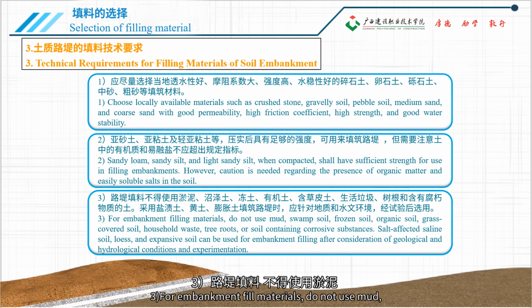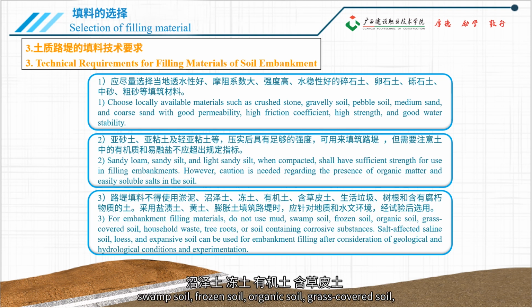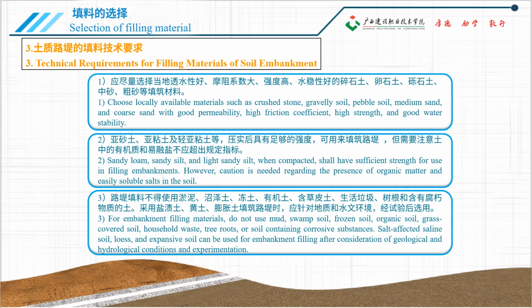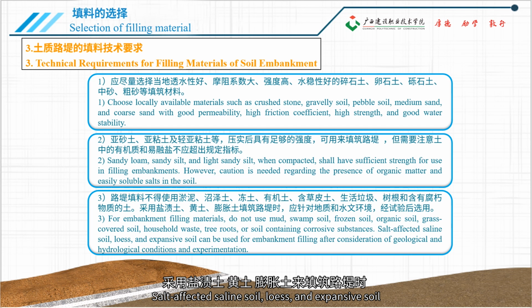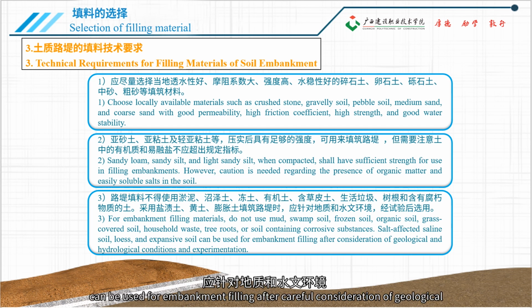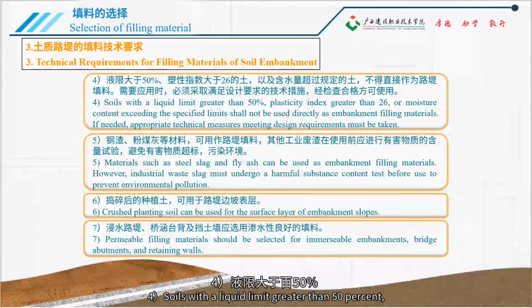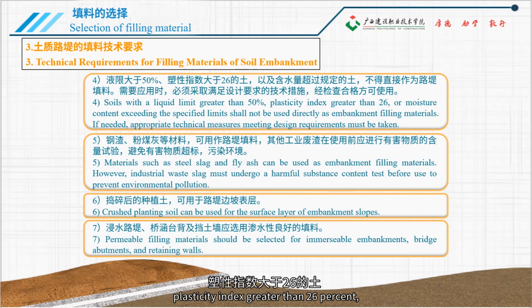3. For embankment fill materials, do not use mud, swamp soil, frozen soil, organic soil, grass-covered soil, household waste, tree roots, or soil containing corrosive substances. Salt-affected saline soil, loess, and expansive soil can be used for embankment filling after careful consideration of geological and hydrological conditions and experimentation.